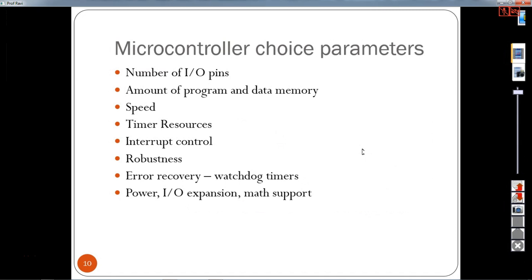And coming to the PIC architecture, it is a Harvard architecture, whereas the microprocessor which we have seen is of von Neumann architecture. In von Neumann architecture you have the CPU and one memory, RAM or ROM. So you have only one address bus to identify the memory, and one data bus to bring the instruction or data, opcode or data, to the CPU.